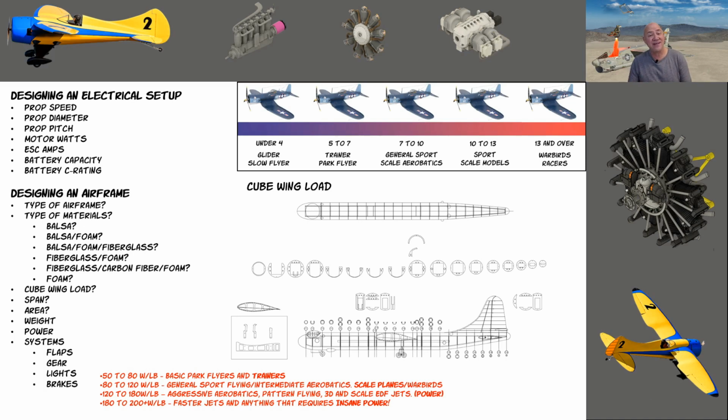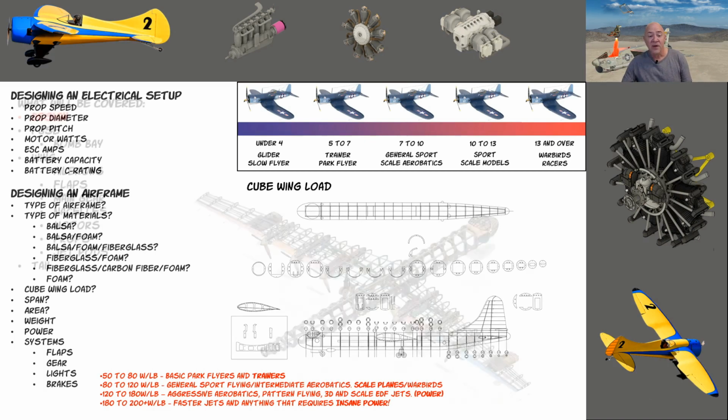A lot of people think I design in 3D. I do for my 3D engines and all of those parts and pieces, but when I'm designing an airframe, believe it or not, I draw it all in AutoCAD first, and then I export that into 3D, extrude it, assemble it and see how it fits. And if it doesn't fit, I go back into AutoCAD and adjust it.